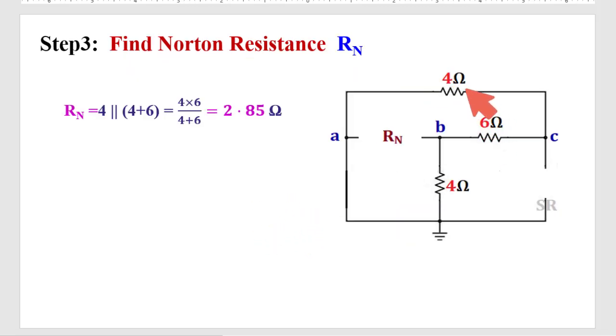Here 4 and 6, these are in series and the combination of these is in parallel with this 4. If we cannot understand it, we can read these things. This is the terminal, we start from here. So say this is that terminal, we start walking from here, we got two paths, this is one path, this is another path. So in one path this is 4 ohm resistance. So drawing this, one path this is 4 ohm resistance, and this is connected with this resistance 6 ohm, and ultimately it comes to terminal number B.